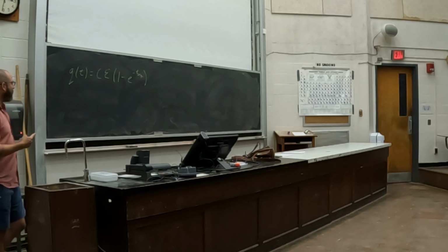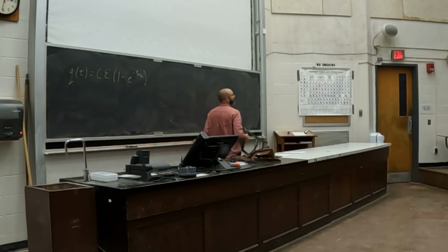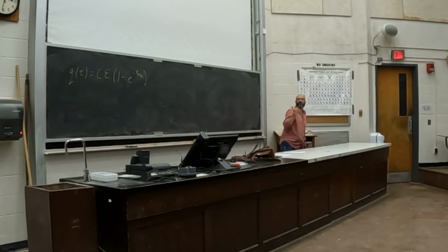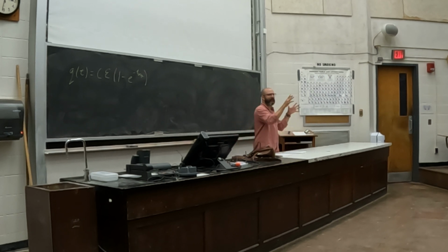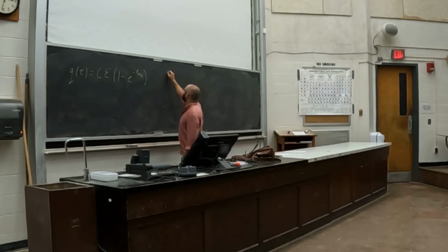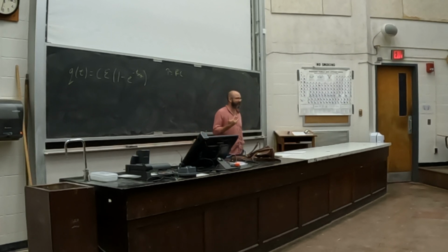RC, right. So of course, if you have a circuit with multiple capacitors and multiple resistors, you can simplify using the same technique we've been using. This R is the equivalent resistance of the whole circuit. C is the equivalent capacitance of the whole circuit. So you might have a capacitor bank in an arrangement of resistors. You do all the work there, and pare it down into one equivalent resistor and one equivalent capacitor. That's your characteristic time, your RC, which we just abbreviate as tau. So this is the charge as a function of time on a charging capacitor.